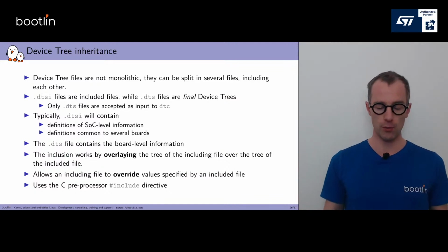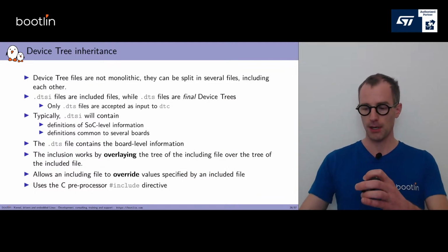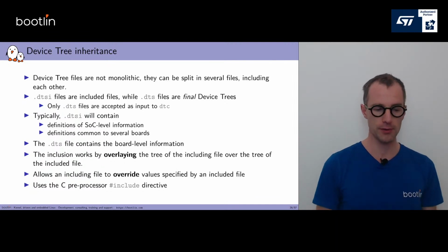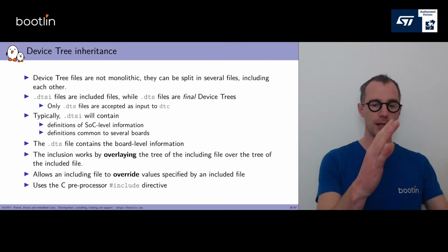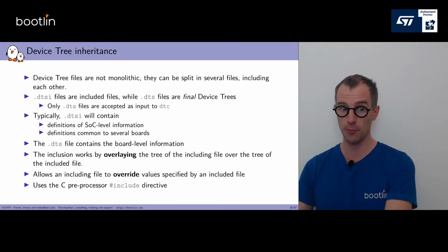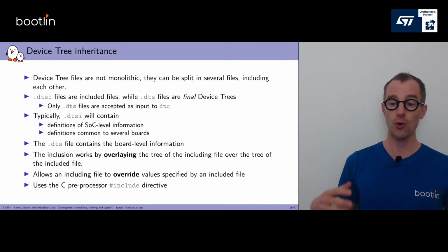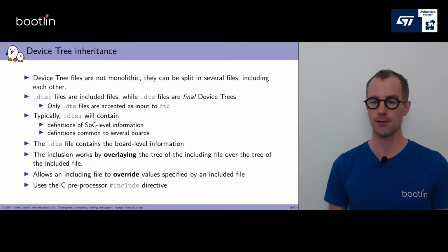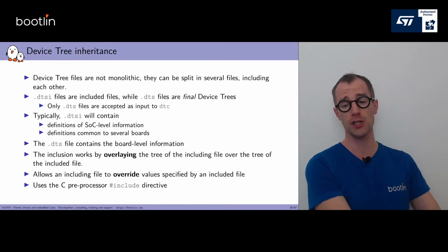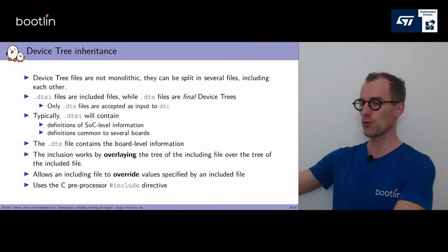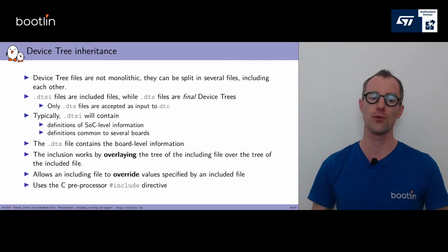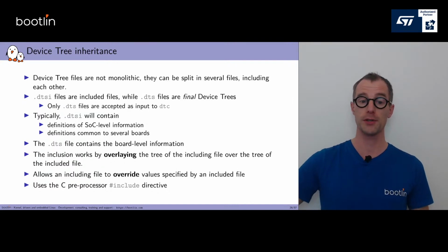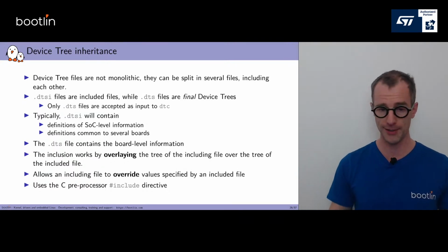So now that we have understood this concept of hierarchy of nodes representing the hardware and matching closely the actual topology of the hardware, how do we write those device tree files? We said there's going to be a DTS for each platform, and you compile it to a DTB, which you give to the kernel for it to understand the topology of the hardware. So far, so good.